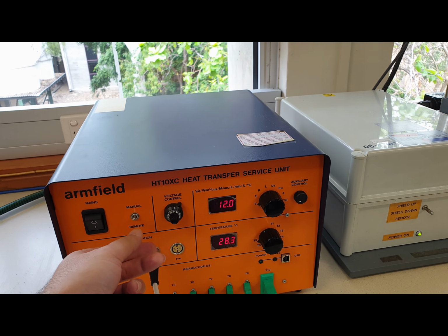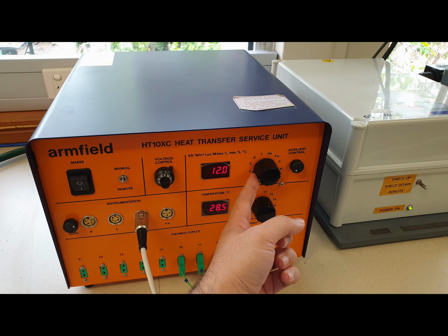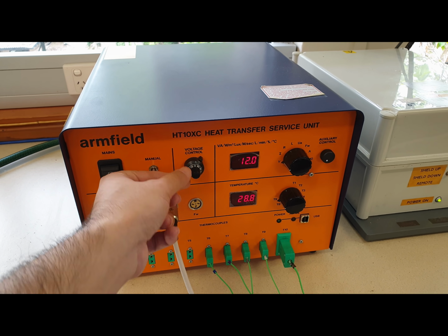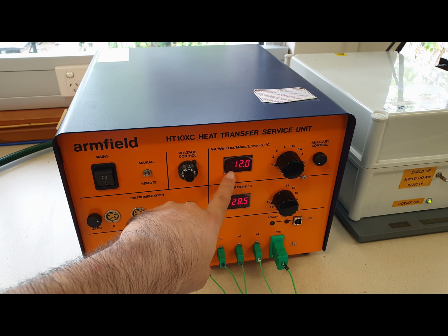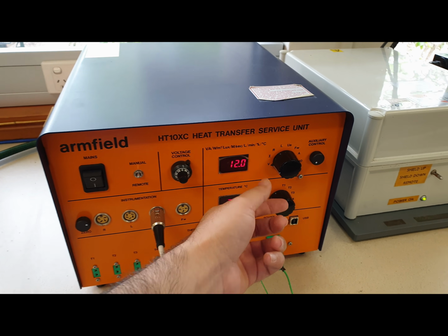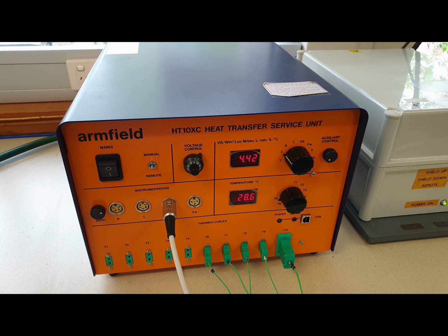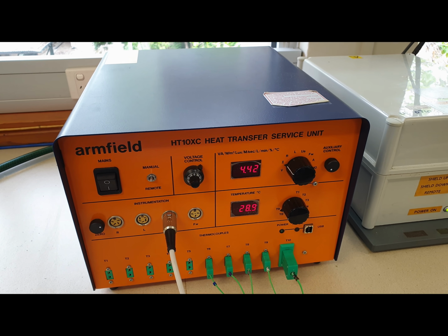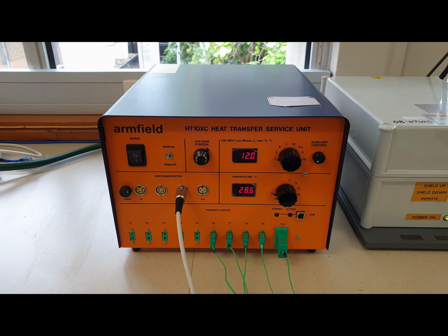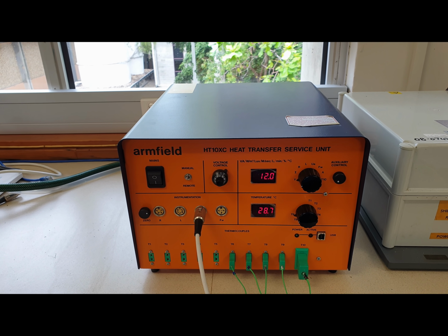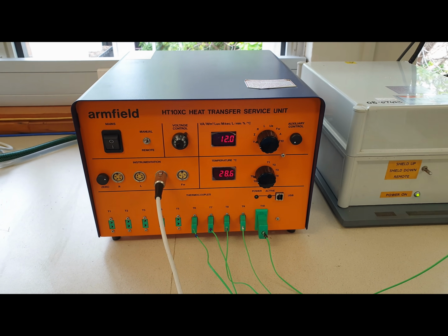Okay, let's see what are the controls I'm going to apply for this experiment. First, I'm going to change the voltage using this knob and this selector. Currently it's voltage, so I can rotate this knob to change the voltage. As you can see, I adjusted the voltage to 12 volts. What is the current? The current is 4.42 amps. So these are the 2 input numbers we have for the heater. So the heater power is going to be that voltage, 12, times the current.